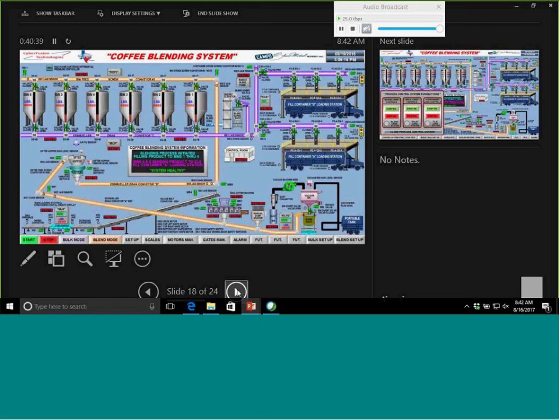So as we get into production, you'll see live product being put on. You'll see the weights going into the silo bins, not only displaying the weight, but also displaying the level within the bin. You'll see 3 different load locations at the very beginning, lower left-hand corner. We have a checkway conveyor belt there, and that's where they load the bags of coffee at that entry point, and from there it goes into a bag cutter where it shreds the bags, and then from there we transport the coffee to the sifter hoppers for cleaning and so on.